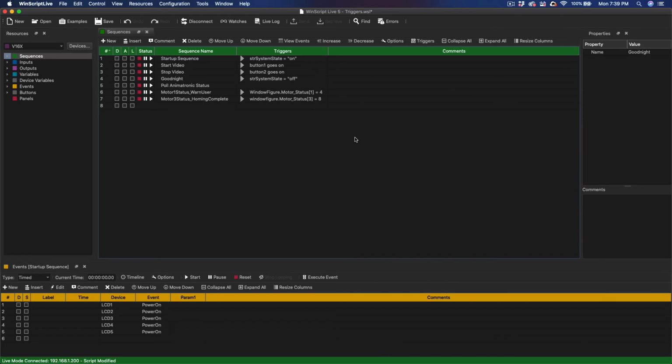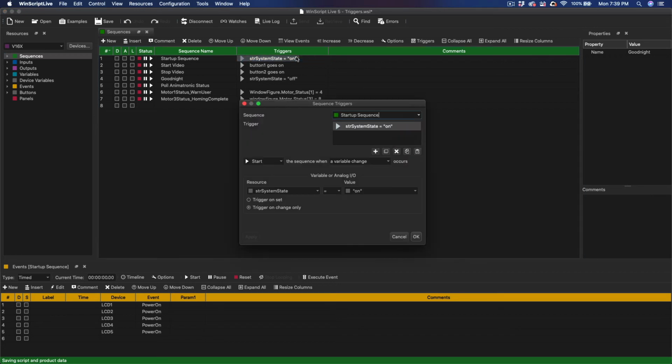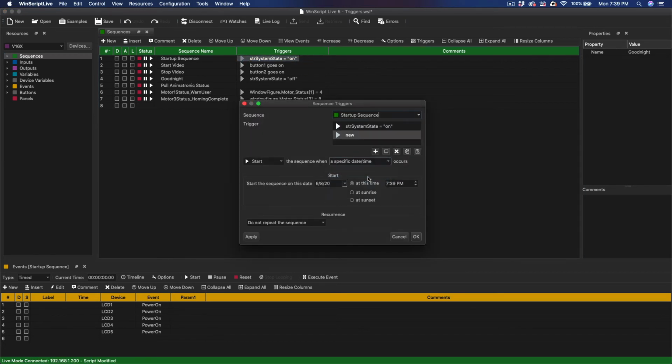Time-based triggers are pretty straightforward. When a time happens, the sequence trigger runs. There are a few unique things you can do with time triggers that we should look at though, specifically sunrise and sunset. Remember how we looked at setting the latitude and longitude of our controller earlier? Turns out that's got hidden value for you here. If you set those values correctly, the controllers will calculate your sunrise and sunset times for that day and allow you to run triggers for those special times.